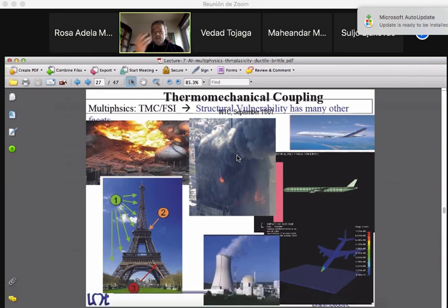Center in France. The symbolic structure would be like the Eiffel Tower. So then you had to have a large deformation, and then there was plasticity and also heat. The pattern of the failure here was really that you had a fire that weakened the yield stress of the particular steel columns, and after that, of course, it was easier for it to collapse. So we were studying the eventual instability problem when you have a large deformation, elastoplasticity plus heat transfer.